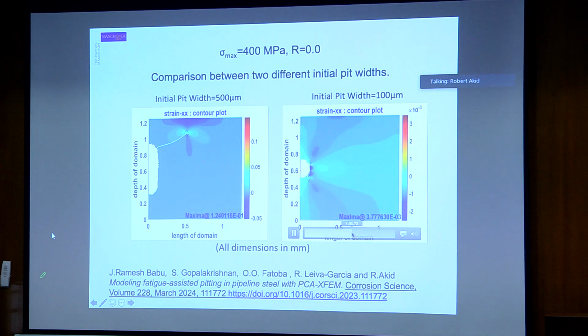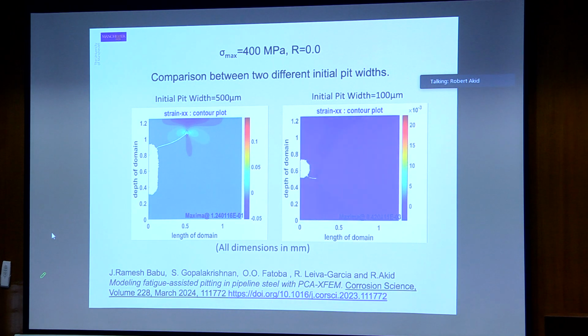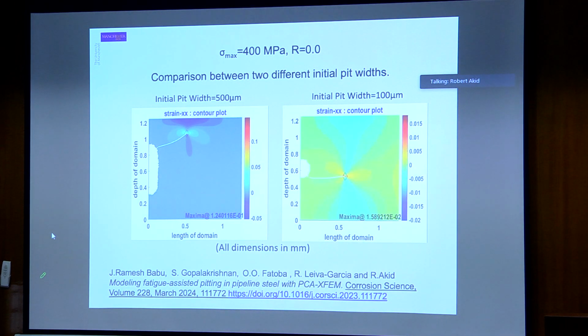I'm going to move this on a little bit, and what we see is that it eventually behaves. What I should say here is the fatigue stress is in the vertical y direction, and the crack is propagating perpendicular, in the mode 1 sense, with respect to that stress.